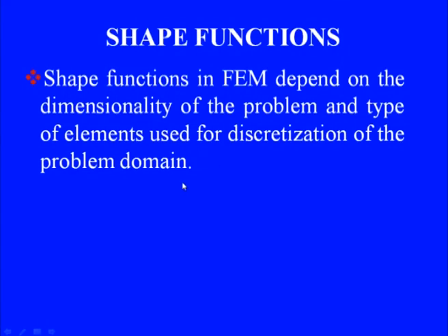For instance, in solid mechanics, we have a set of functions which are used for plates and shells and so on, but we would focus primarily on the most popular shape functions of polynomial type. And please remember, the shape functions in finite element analysis depend on the dimensionality of the problem, whether we are dealing with a one dimensional, two dimensional or three dimensional problem. In each case, we will have a different shape function.